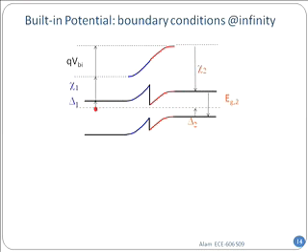Now, let me then talk about how to calculate the built-in potential. I have the solution already, right? I have drawn a graph and I have solved the Poisson equation. Now, let's see whether you agree with this statement. Maybe I try one more time. That in equilibrium, if you want to calculate QVBI, you realize in equilibrium the Fermi level is flat throughout, and delta 1 plus chi 1 plus QVBI, that height must be equal to chi 2 plus Eg2 minus delta 2.